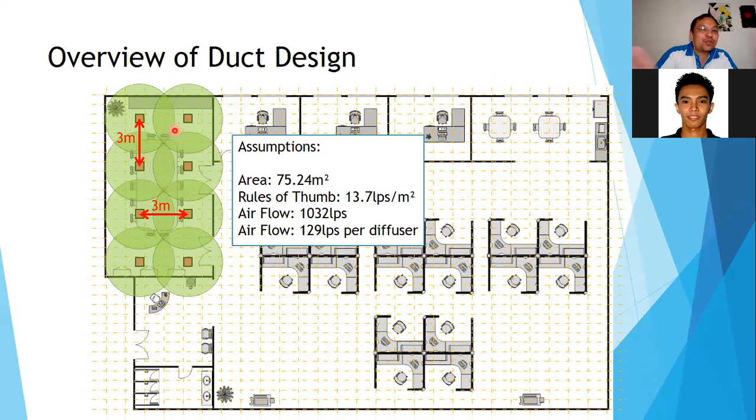So engineer, why don't I just adjust all of these 8 diffusers so that there's no hot spot? On the other hand, if I reduce the hot spot here, I will have a hot spot on this side. So this is the most efficient way for you to distribute your air. Air distribution won't be 100% perfect or 100% no hot spot, but at least you get the most out of it, the most efficient design that you can get.